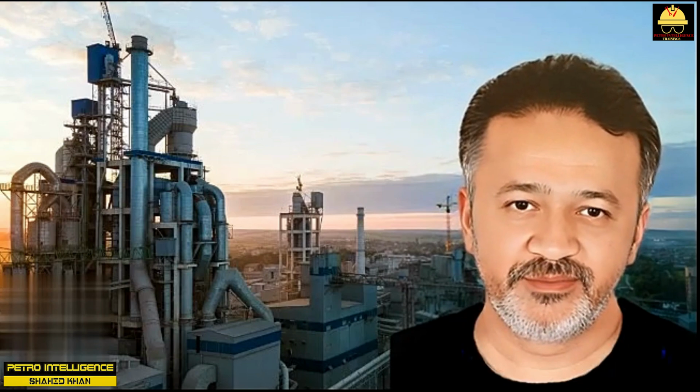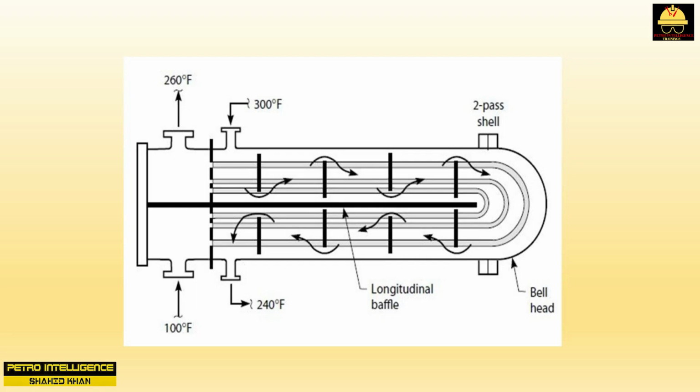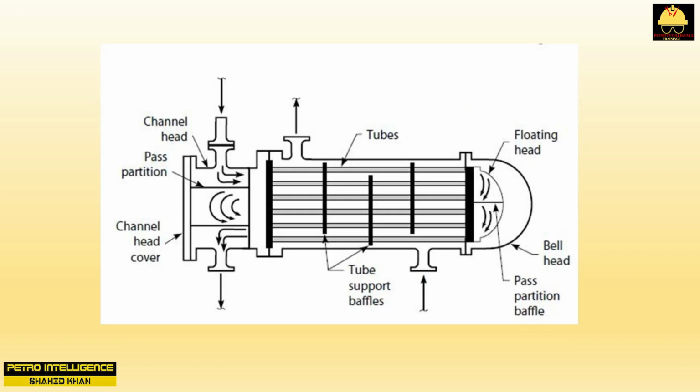U-tube bundles. This picture shows a U-tube bundle. Cleaning the U-bend of such a bundle is quite difficult even by hydroblasting the tubes with a jet of water. My main objection to U-tube bundles is not the difficulty in cleaning, but the fact that such bundles cannot be inspected after cleaning to verify that the tubes are actually clean. In a floating head bundle as shown in the picture, looking down the straight tubes with the floating head removed allows the verification that the tubes have been completely cleaned.